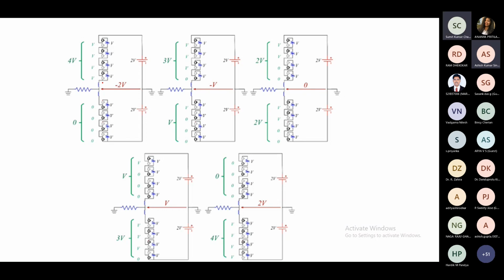The lower the switching frequency, the more the deviation between each other. Why, that I cannot discuss now. So what will happen? Even if the charging current is coming, these capacitor voltages will start differing from each other. So that demands something called cell level control.